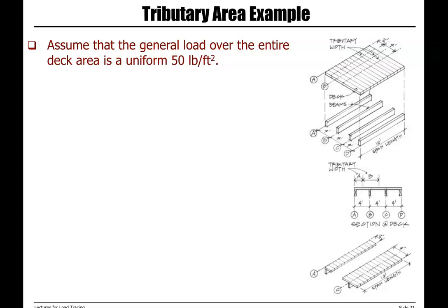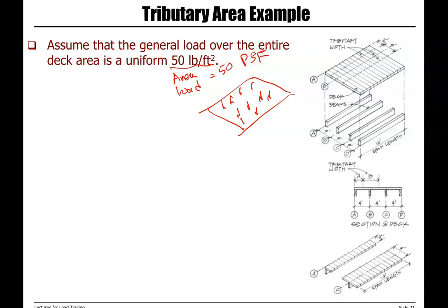So in this example, we have an area. The general load over the entire deck area is a uniform 50 psf. So we have an area, and on this area, our deck, the area load is 50 pounds per square foot.